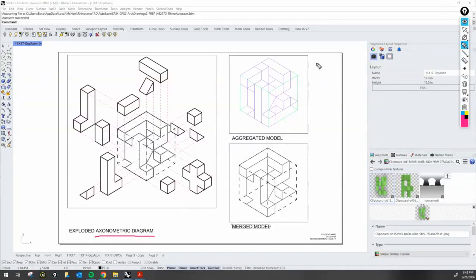So we're going to change color so that we can assign line weights, as I've done right here, and line types, as I've done right here and right here. We're going to be looking into how to generate these drawings using the Make2D command and maybe a few new commands along the way. Okay, so let's take a look.